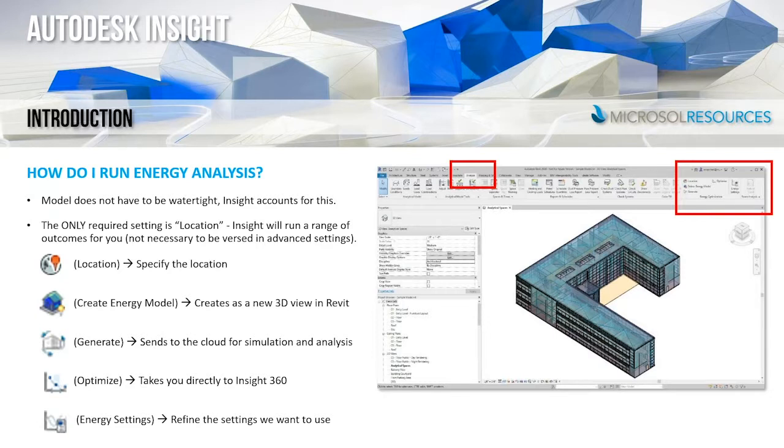Where other energy modeling software requires more stringent enclosures. And again, this can partially be the reason for a majority of energy analyses taking place toward the end of the design process, when the Revit models would be near completion. Insight actually allows for inconsistencies and gaps in the model, and we can set the tolerance for the simulations in some of the settings that we'll review later.